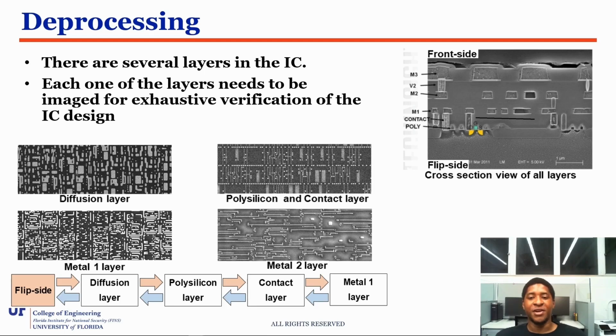This layer is very important because it has the distribution of certain materials that contribute to the overall performance of the IC. We also see the polysilicon layer, which is a form of silicon, and is used to create the conductive parts and the structures within the IC. It is very essential for the functionality and connectivity of the device.